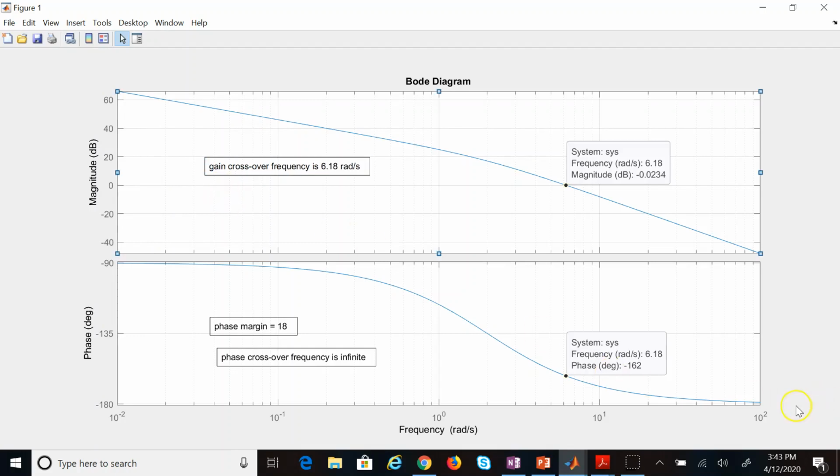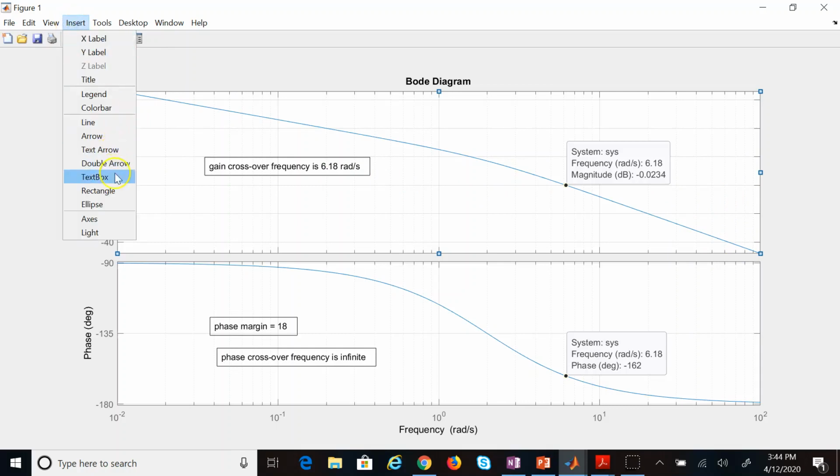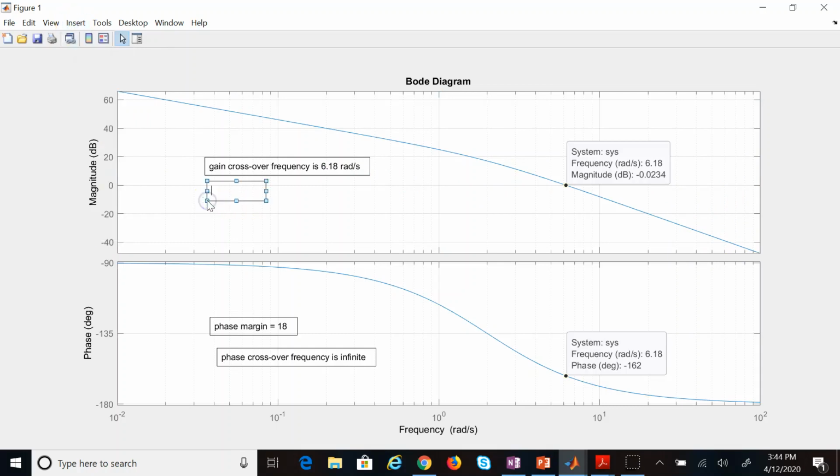And what is gain margin? When omega goes to infinity, what is the magnitude of the system at infinity? Well, it's infinite, of course, because this guy is going to infinity, negative infinity as well. And then opposite of that, the magnitude with the negative sign is the gain margin. And so what is gain margin in this system? Yes, the gain margin is infinite.